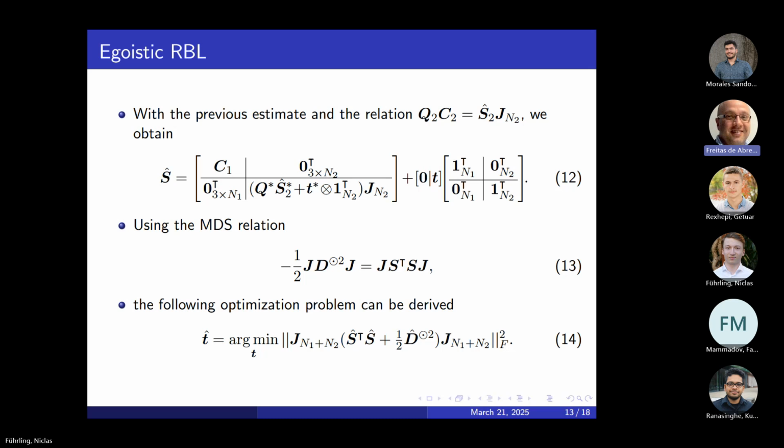Can you elaborate on the possibility of improving the estimate of the rotation matrix Q by adding a constraint that makes sure, because as you know, the values of the matrix are not fully independent, right? Yes, exactly. Maybe to explain first for the others. So what the professor means is that if you have such a rotation matrix, it has to be in the special orthogonal group, which means that Q transpose times Q has to be identity. Otherwise, it's not a valid rotation matrix.